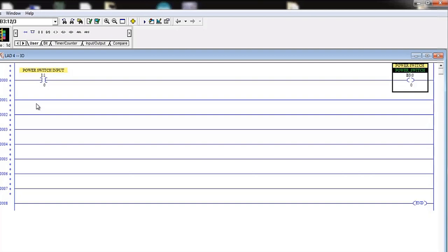The wise, smart programmer will pull all of their I/O out of the logic and set it aside somewhere in a ladder or 4 ladders dedicated to I/O. And I:1/0 is going to appear one place and one place only within this whole program, and that is right where it is right now in ladder 4, rung 0.